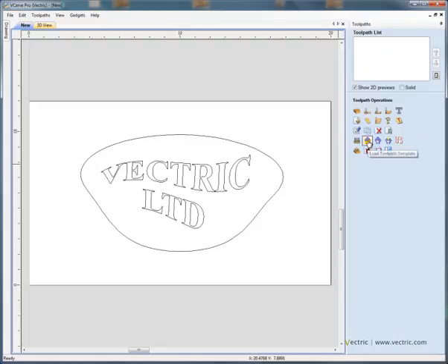So click OK. Here we've got the toolpath operations, and the first line of toolpaths are what we refer to as the 2D toolpaths, so creating simple profile toolpaths, pocketing, drilling and quick engrave toolpaths. The second row are the 2.5D toolpaths, so V-carving, fluting toolpaths, the texturing toolpath, raised prism toolpaths and the inlay toolpaths. If you're working with a Spire, there will be another row of toolpaths in here for 3D toolpaths.